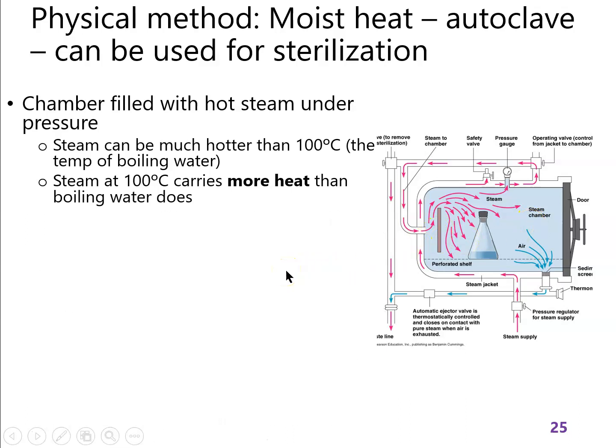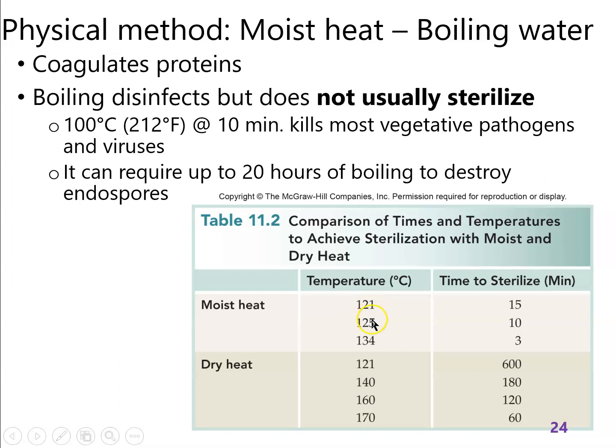The other thing I'd point out about autoclaves is these are the temperatures autoclaves work at. So typical autoclaving of something like water, if you want to sterilize water or growth media in a laboratory, use 121 Celsius. An autoclave can typically also achieve a temperature like 134 Celsius, but not at a high enough pressure to safely do water.